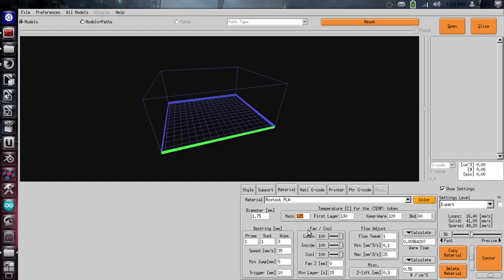This is going to be the temperature for your entire 3D print, other than your first layer. These are values that you're going to want to pick from among the recommended ranges for the material you are using. Just go ahead and ask Google about your material and you will find its melting characteristics online. I guarantee it. Start with some recommended values and adjust as necessary.